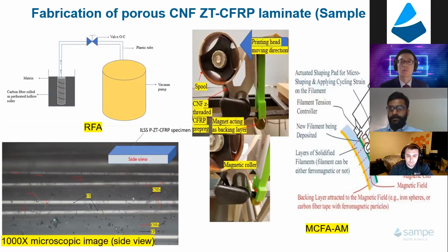So we end up using acetone to slow down the curing so we can disperse it. It was a normal approach for handling nanoparticles in RTM resin or some kind of slow curing resin. Again, it becomes a problem for fast curing resin. How do you remove the acetone without it curing during the removal? When you have a lot of acetone, the resin never cures.